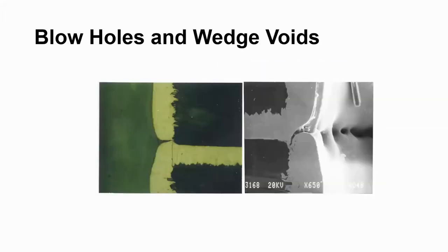Another situation that can happen, in the boards that you can see on the right here, is that this may have passed electrical test at the fabricator, but because of the wedge void that you can see going around the hole here, it goes out to the circuit board assembly facility. They go through wave solder, and lo and behold, because of the thin plating like you see here, or the slight potential void or fold here, what's going to happen when that board hits the molten solder and it interacts with the flux? Chance for a blowhole or outgassing because the copper wall is so thin here.